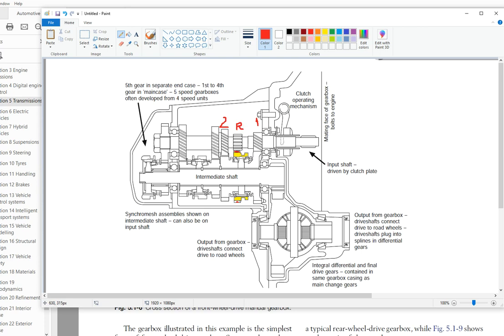It could be either an in-between position of the sleeve where I have the reverse pinion with the idler, which is not shown, and the teeth of the synchronized sleeve meshing, where I may have the idler being brought into engagement.